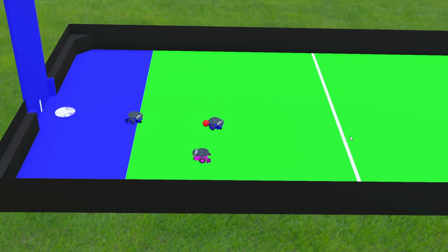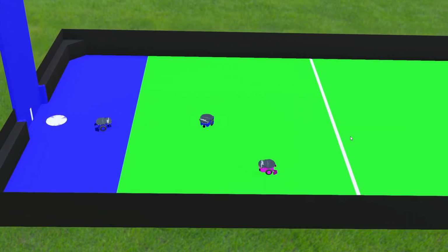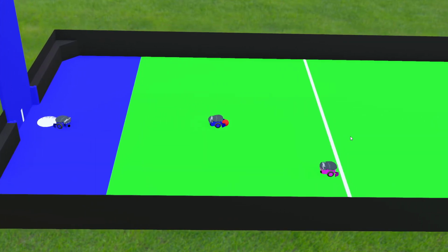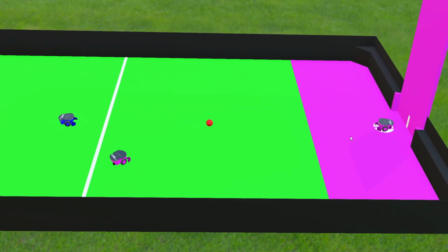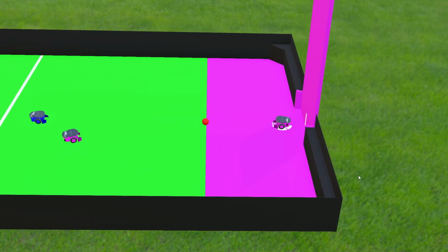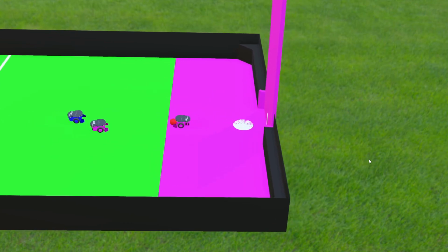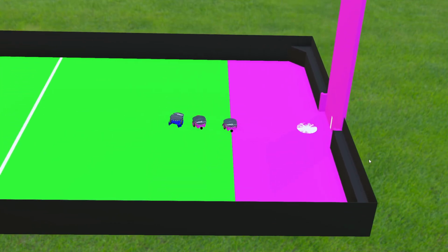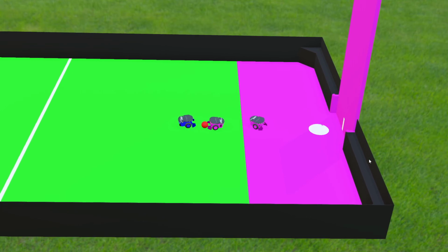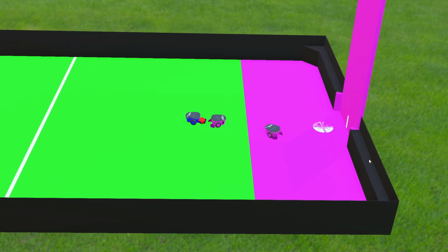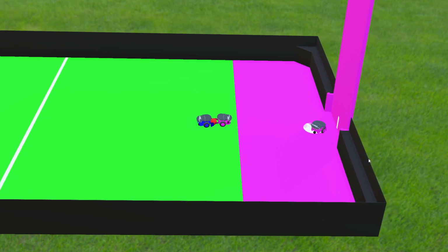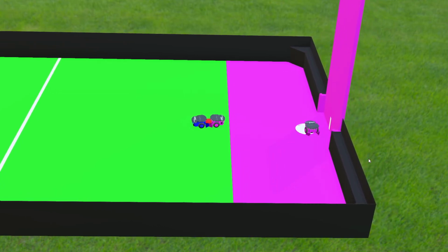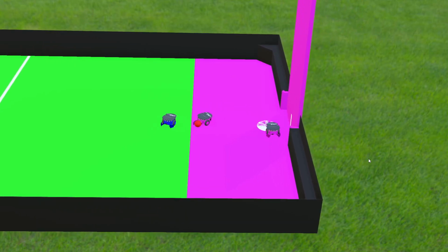So if I were to do this simulation again with different robots, I would probably choose a different ball or a bigger robot, and then have some sensors that are lined up with the ball in height, and some sensors that are slightly higher, in order to sense objects that are further than the ball. That way you can avoid objects that are beyond the ball.